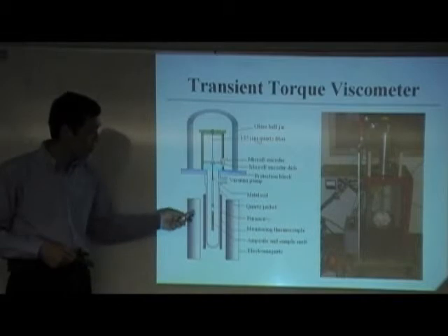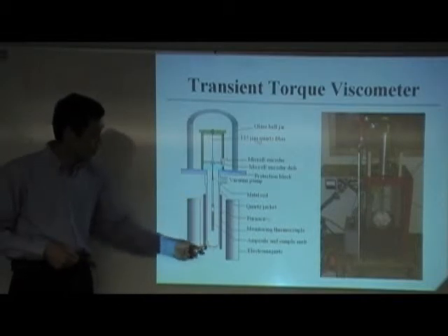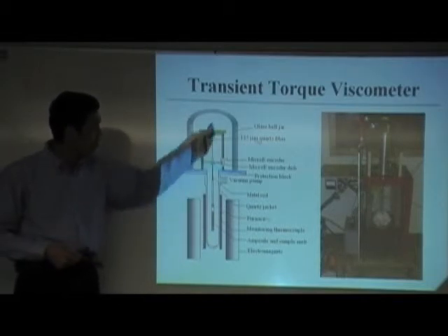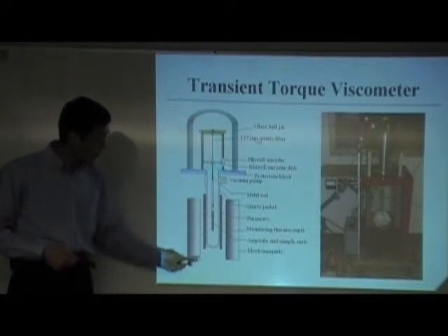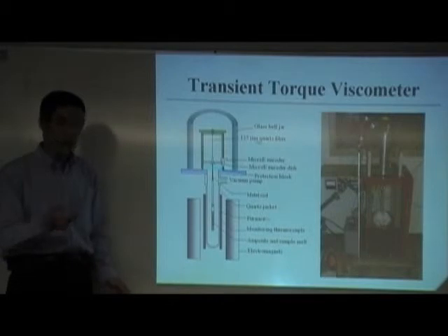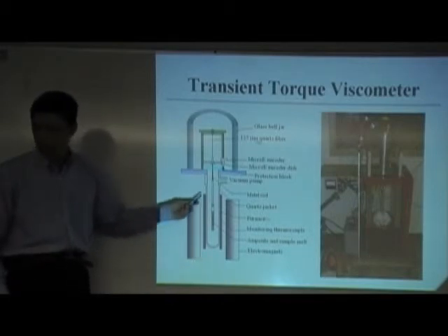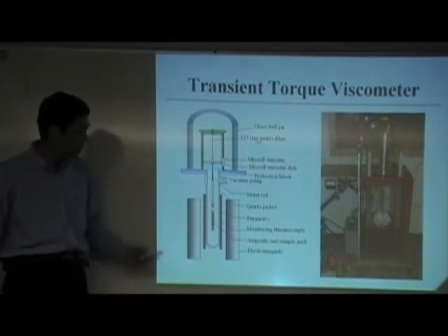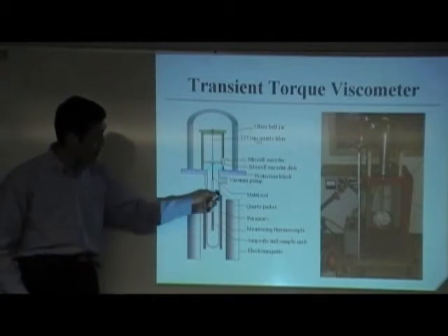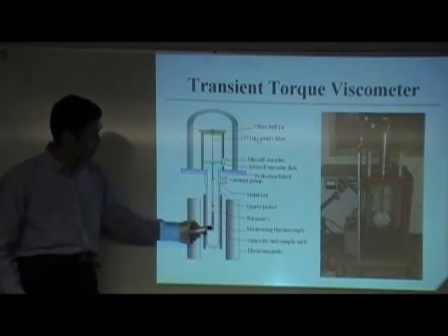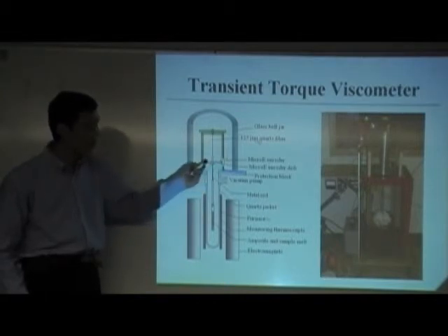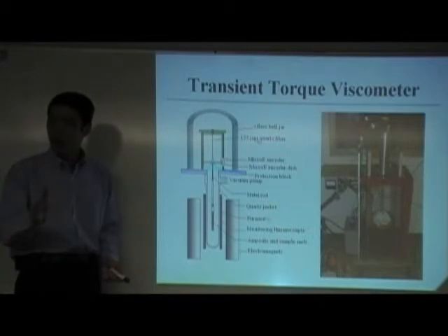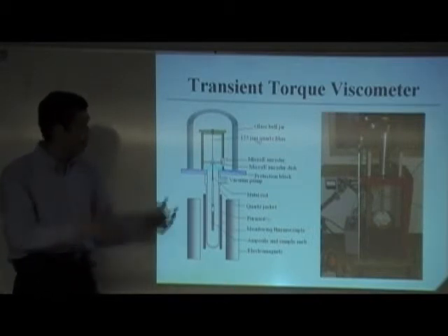And all the others: you have a furnace, it's a quartz in a vacuum, so there's a vacuum pump. The whole thing is in a vacuum system. How you rotate the liquid is by electromagnetic force, so you have an electromagnet here and a high temperature furnace. And this is a quartz and then a rod, going through an encoder. You measure very small angular change, so you can see the vibration of this.